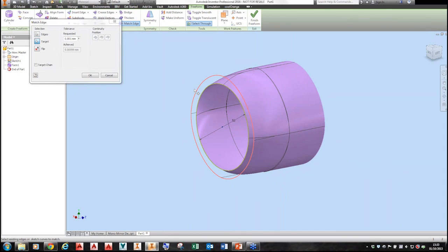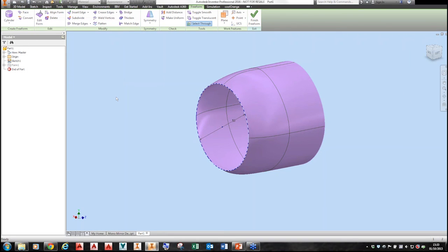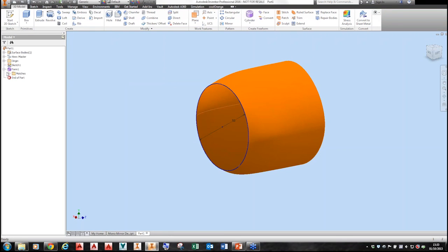So if you've got a certain profile that you want your component to match, you can then tie it in. So you can obviously put a parameter to this dimension, and that will tie it in nicely to it. Later on, sometimes parts might move away, but then you can always go back in and refresh that command. So within here, you've got your matches. So in the future, if I tweak the surface and it didn't quite line up again, you just go back into the command and then find these matches and rematch them back to that sketch.